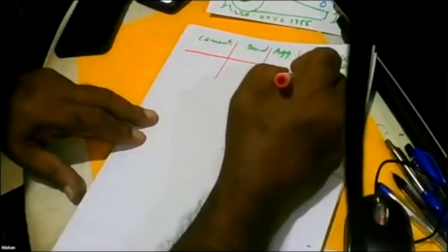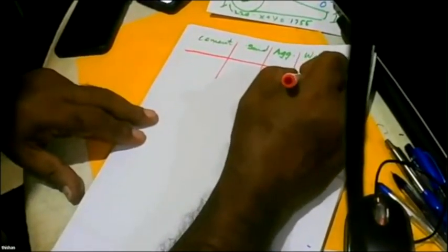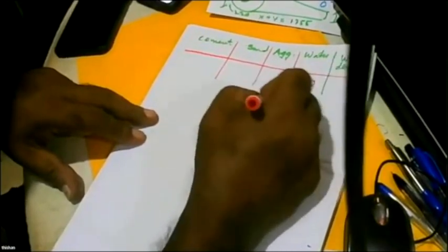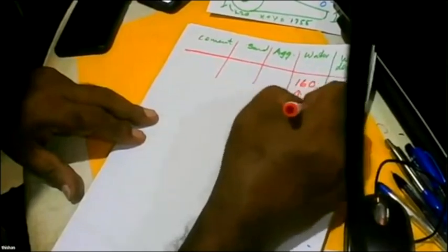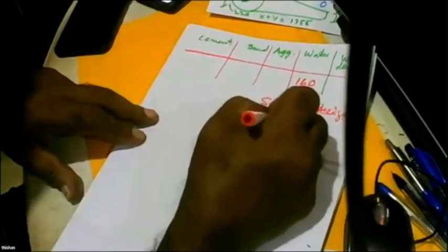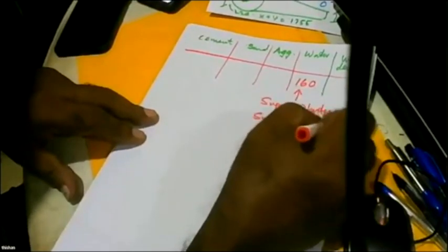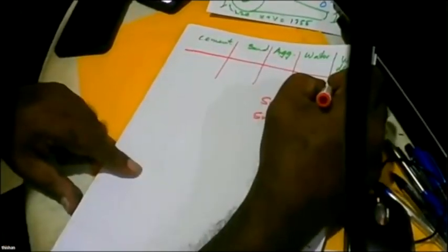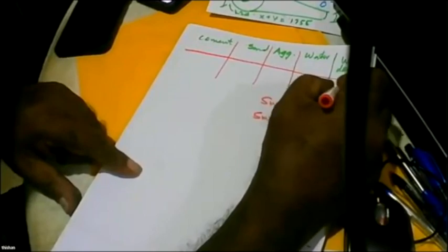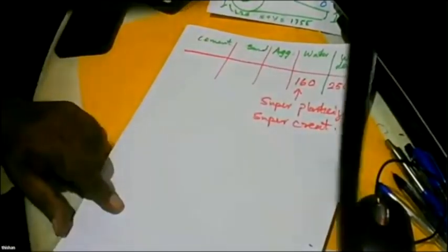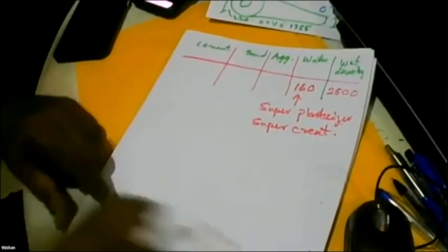So cement. Now I'm going to use an admixture. So the first thing you enter is admixture, 160. It's a superplasticizer, like Supercrete, made by Millennium Technologies. That's a trade name. And so density. As long as I don't use fly ash, density is 2500.